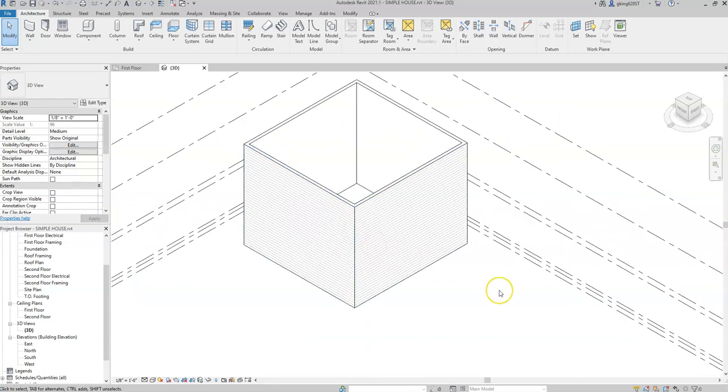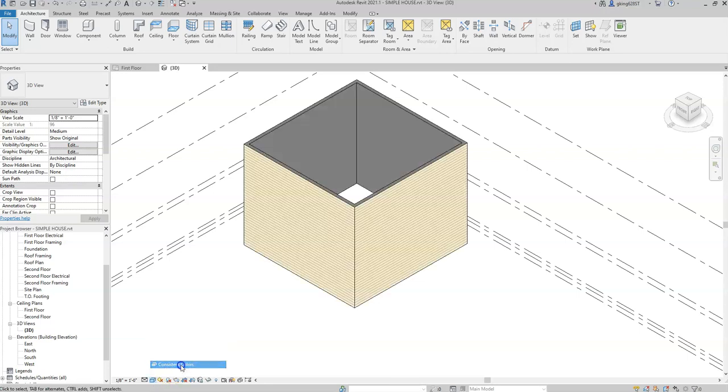All right. Now another thing that we can do here is change the view of our building. Right now it kind of looks like a pencil sketch, right? But let's say that we want to make this more colorful or look at it in a little more detail. Because what we're seeing right now is on the outside of the building, we have all of these parallel lines here. That's actually our wood siding, and on the inside, that's our sheetrock, our inside finish. So to change the way this looks, because sometimes this may get a little confusing, I go down to the bottom of my 3D view here, and I can change my visual style. So I'm going to put it on consistent colors.